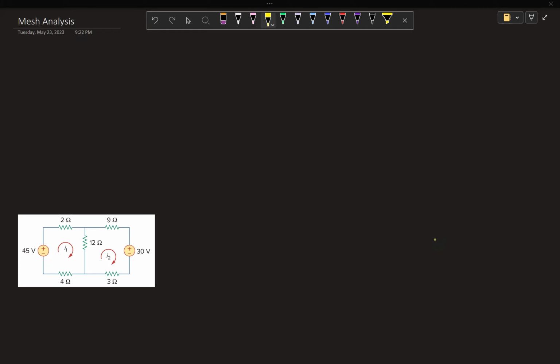In this video, I'm going to be going over mesh analysis, which, like nodal analysis, is just another standardized circuit solving technique. And while nodal analysis was basically just the application of Kirchhoff's current law in conjunction with Ohm's law, mesh analysis is instead based upon Kirchhoff's voltage law, again with the usage of Ohm's law.